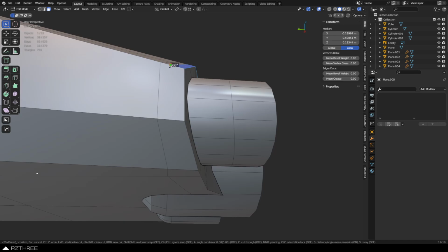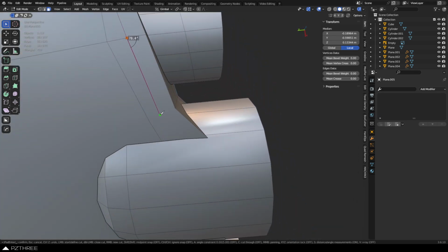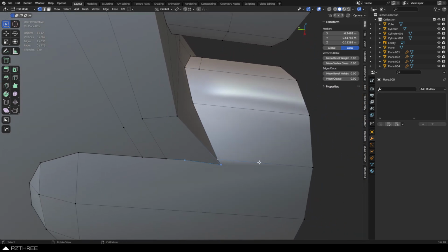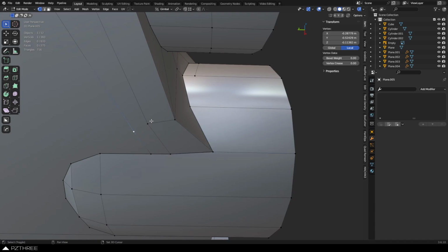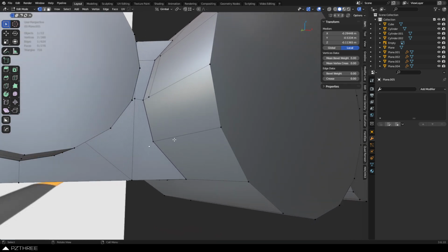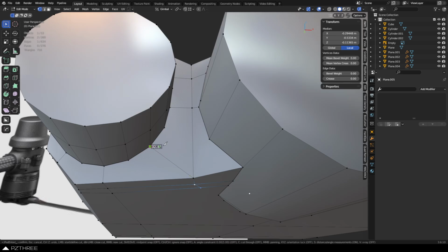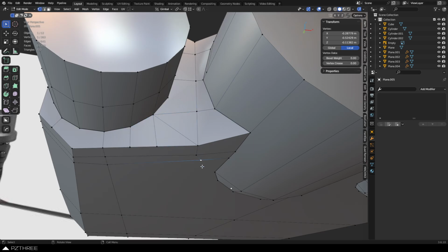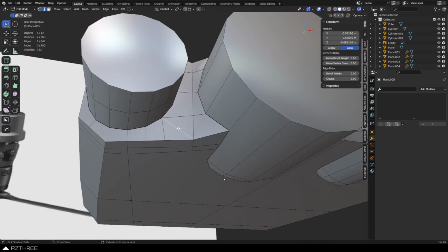A lot of you guys were asking about how do I know when I'm doing loop cuts, I'm not screwing my model up or something like that. Usually if you're working with n-gons or triangles, a lot of times you can't loop cut through it. So actually, I'm going to just merge those to that. I think that'll work out fine, even though it changes the shape slightly maybe, but it's a little simpler. Try to keep things simple if you can, but not always possible. Sometimes you got to go up in resolution, so do that. But when you have n-gons and triangles, you do not run loop cuts through n-gons and triangles usually.